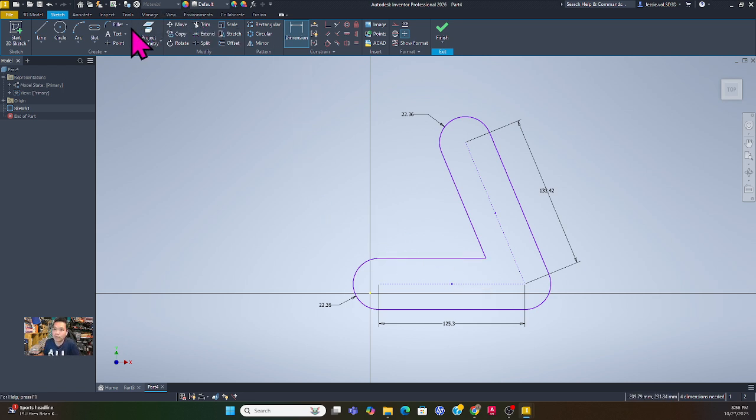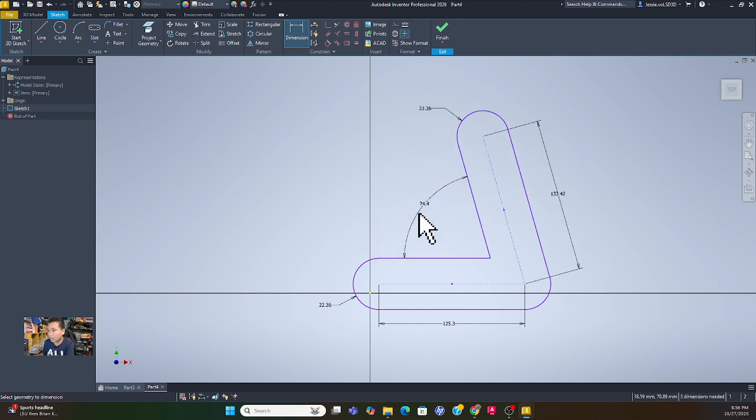All right, the next thing we're going to do is we do have a dimension of this angle. So click on those. This is going to be 74.4, enter. And also we do have a fillet of 20 right here. So I'm going to do 20, hit enter there, and then I'll select my two sections here, hit escape. That is a 20 right there. Just going to drag it up a little bit so it's up here instead of down there. Okay, and that's my angle.